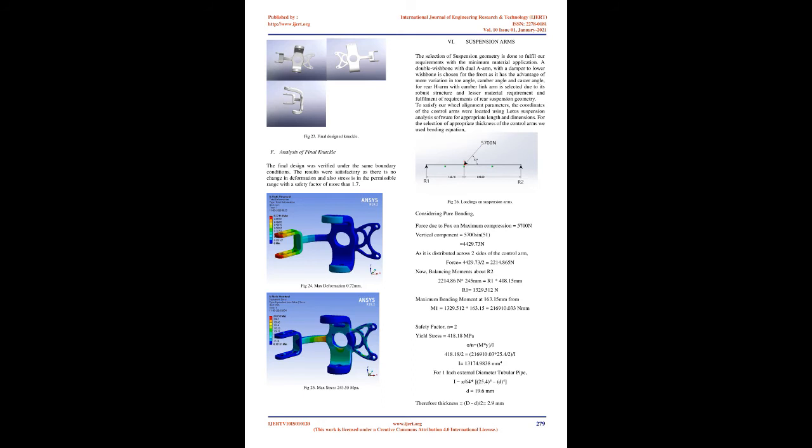Sharp corners and edges and curved surfaces are the locations which are very likely to have maximum stress concentration, and therefore it becomes very important to have a good quality mesh in these areas. To fulfill this purpose we have used certain mesh features provided in ANSYS Mechanical. A. Mesh defeaturing. Small corners can deviate the results by having maximum stress concentration. To avoid this deviation, mesh defeaturing is used. It removes small corners. The value of mesh defeaturing taken was 0.4 mm.